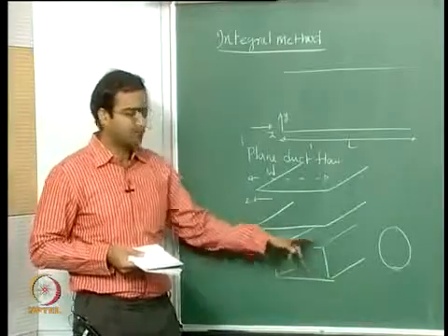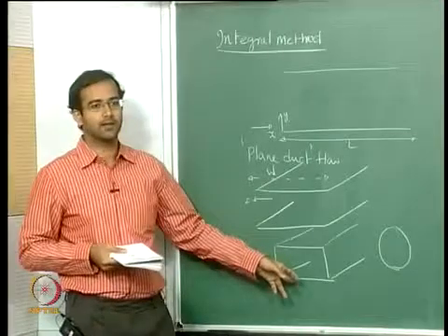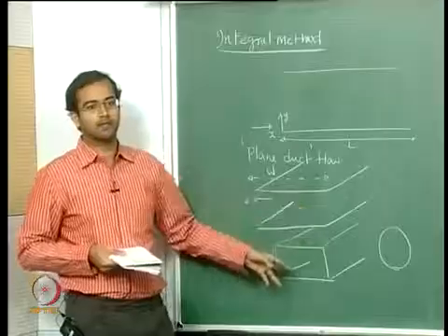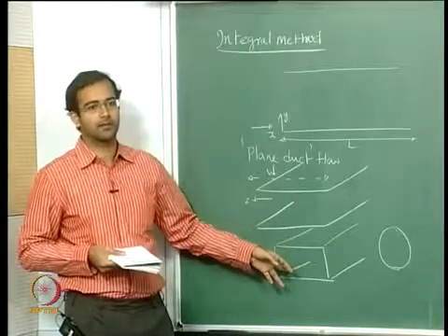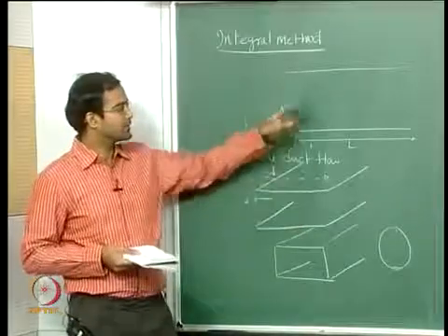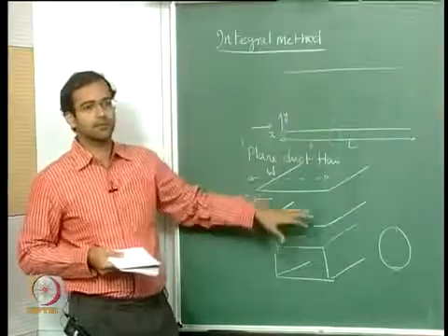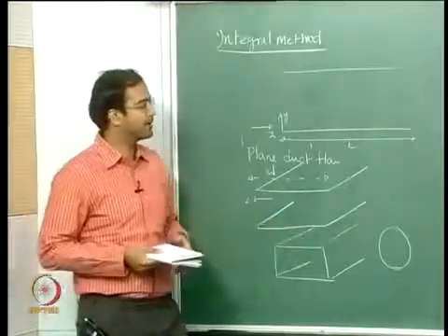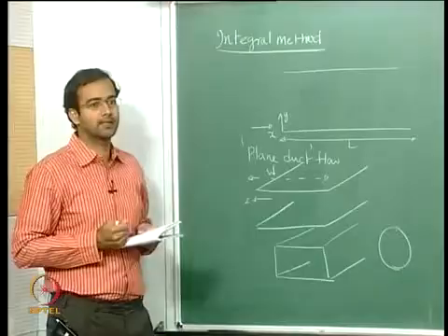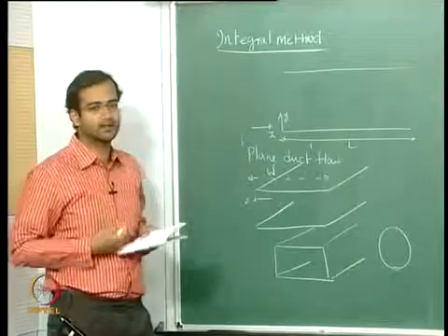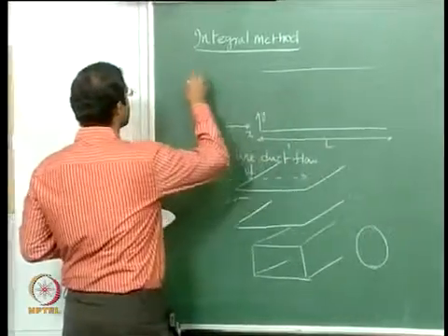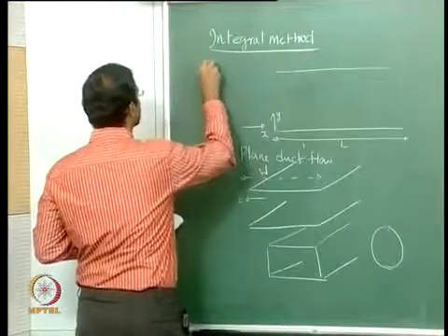Therefore you have to solve this in all 3 coordinate directions, and the limiting case, the 2-dimensional case of this duct with a finite cross section, is your plane duct flow. This is where we consider the 2-dimensional approximation of the plane duct flow, where you look at the 2D flow varying along the x and y directions only, without looking at the z direction. This is nothing but flow between 2 parallel plates, or a plane duct.